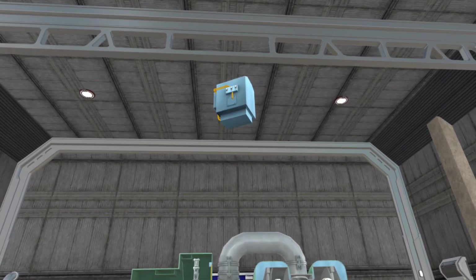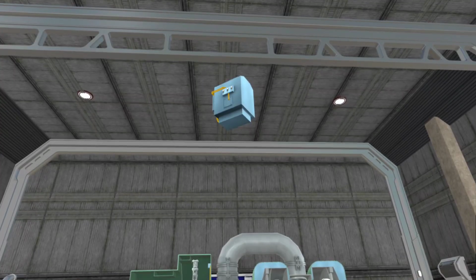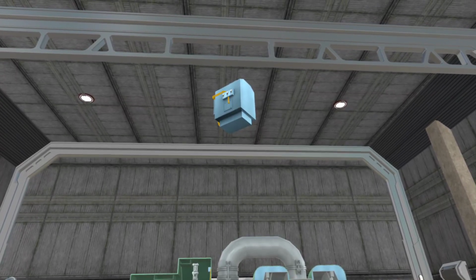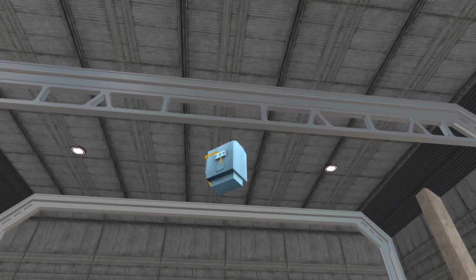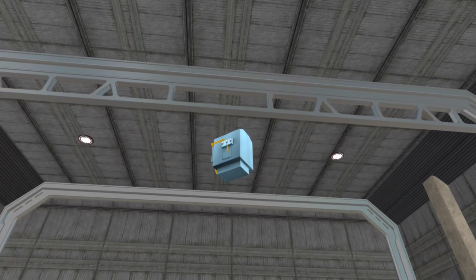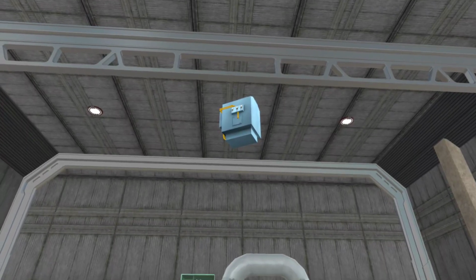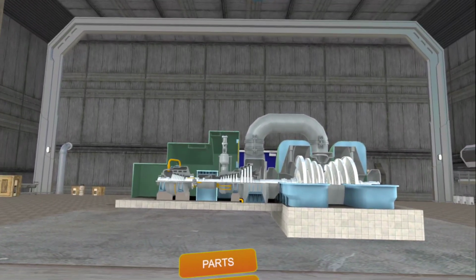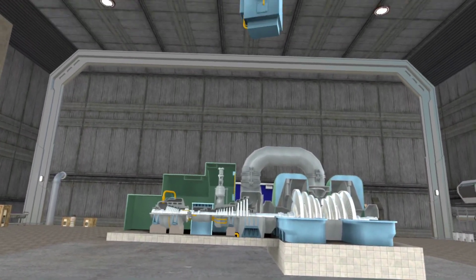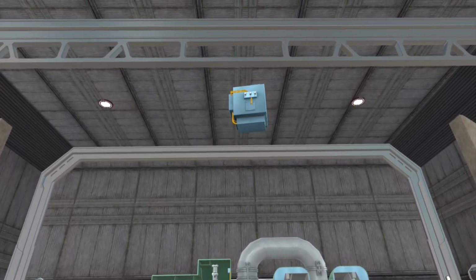Similarly, when the load or the demand on the grid is less than the supply to the grid, the frequency tends to go above 50 Hz and the speed above 3000 RPM. It is the function of the governing system to maintain the frequency at 50 Hz and the speed at 3000 RPM in a free governing mode operation, that is FGMO.